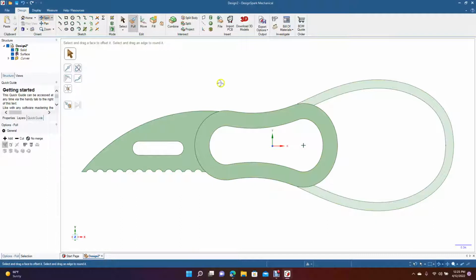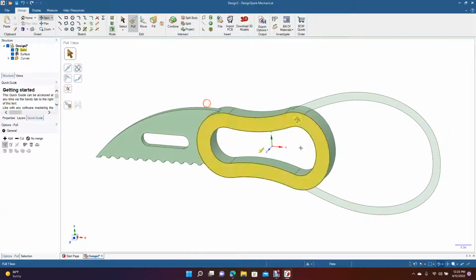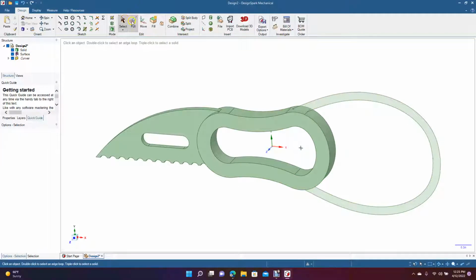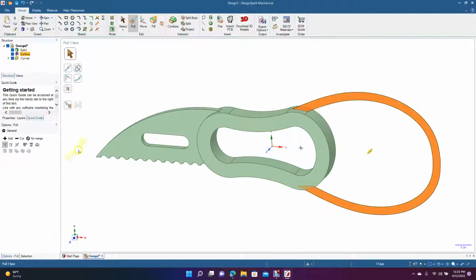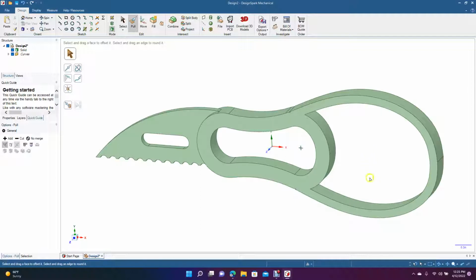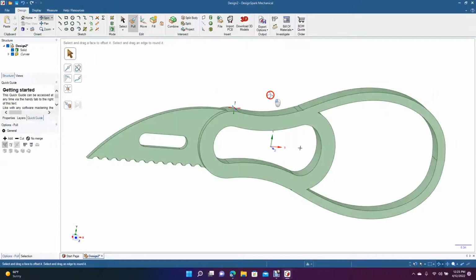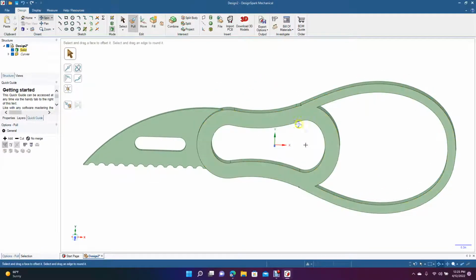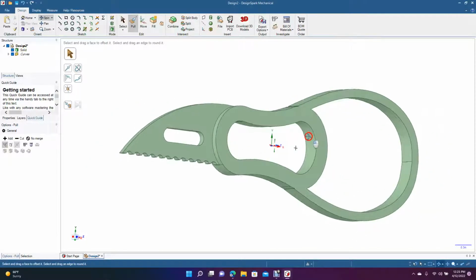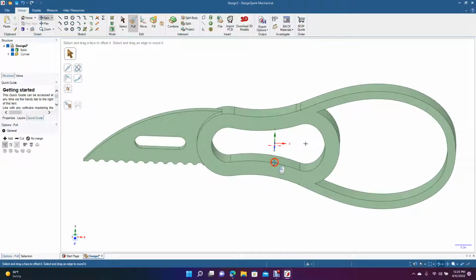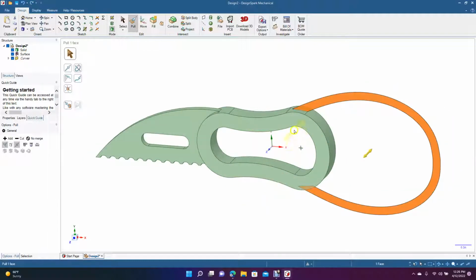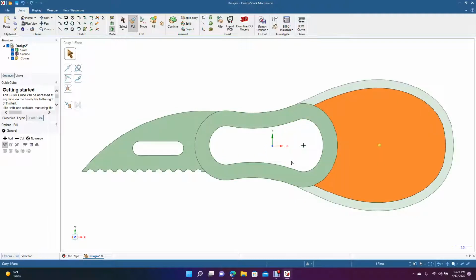Let's go ahead and spin this. So we want to add a little bit of thickness to that. So we'll go ahead and go to pull, we'll click there. We're going to come over here to pull from both sides, and then we'll type in 0.3 like the mid part. Spin this. Not real crazy about that little piece right there, but let's undo that.